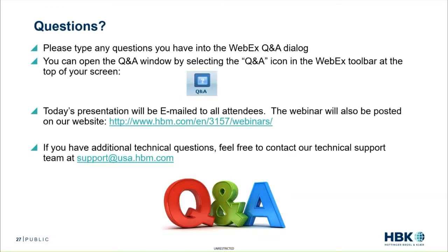Great. More questions. Is it possible to add EtherCAT to an existing mainframe? It is, as long as your mainframe either has a carrier card with an empty slot in it or an empty slot, because the EtherCAT option lives in what we call a carrier card for the frame. So if that's something that's of interest to you, it can definitely be added in the field. You just order a carrier card with EtherCAT, and we ship it to you, and you power down the frame, slide it in, and then power it up, and you're ready to go.